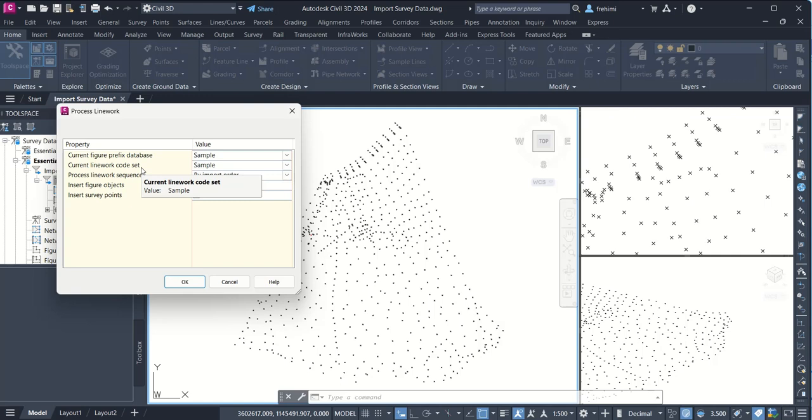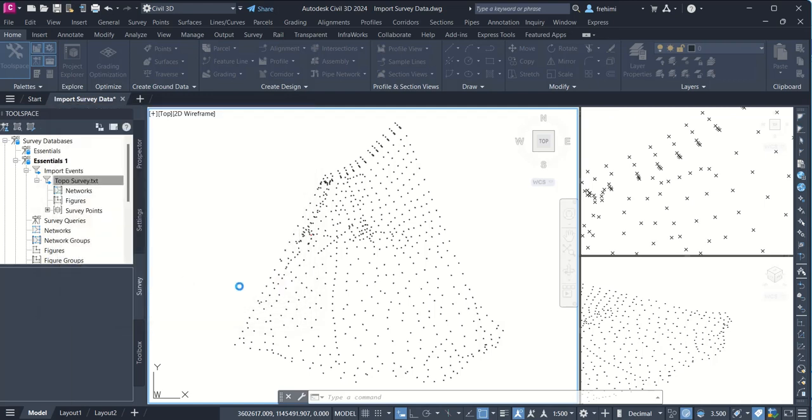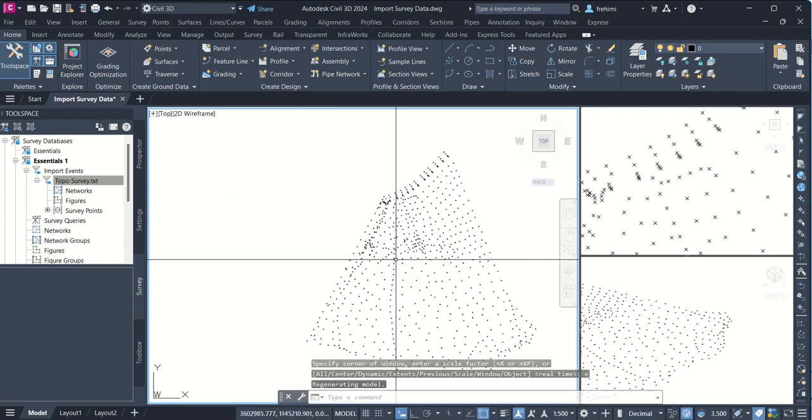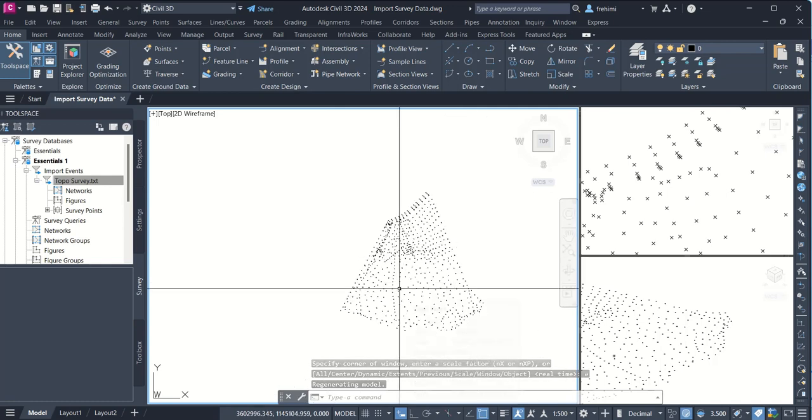For example, if you define a wet area, and you define it as a closed area, Civil 3D, when you process the line work, will link these points. Of course there's a logic how to define them in the description column to link them in the correct order, so that it connects them one after another correctly. Now if you run it, as you see, where are my points? Nothing changes, right? I'm gonna tell you why.